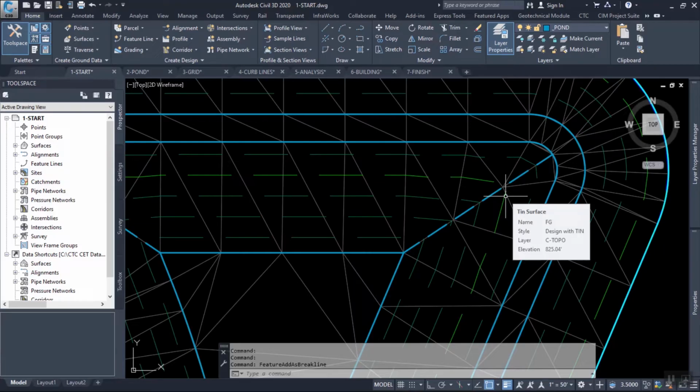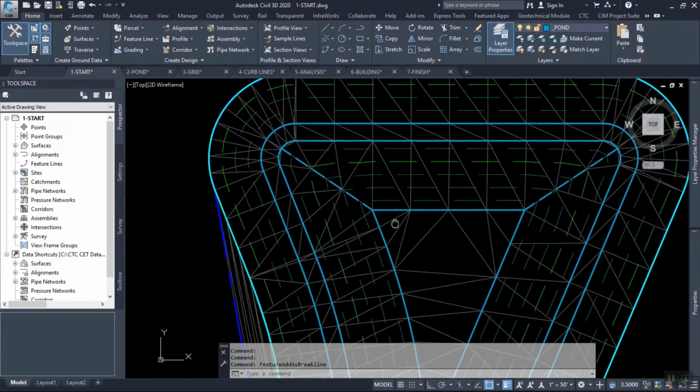When you swap edge, it's this kind of Band-Aid fix to it. And then when you come next to it and throw a break line over that swapped edge, and then you delete a line, mysteriously you start getting holes in your surfaces. This weird stuff starts happening. Don't do the Band-Aid fix, the swap edge, the delete line. Do this instead.